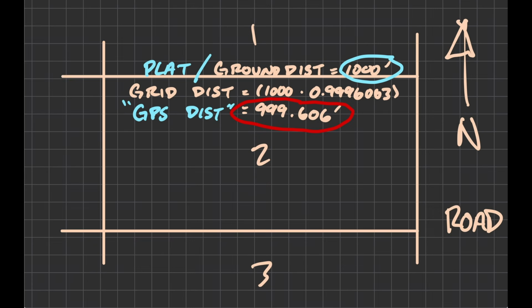Let's look at another example. If we surveyed a 1,000-foot property line with GNSS and left it in UTM, and that property line was originally established in ground and reported that the new length is 999.6 feet, you can imagine that property owner might be upset that you just shrunk his property by almost half a foot. Now imagine if we staked out building corners incorrectly by almost half a foot. And this is just at 1,000 feet or 300 meters.